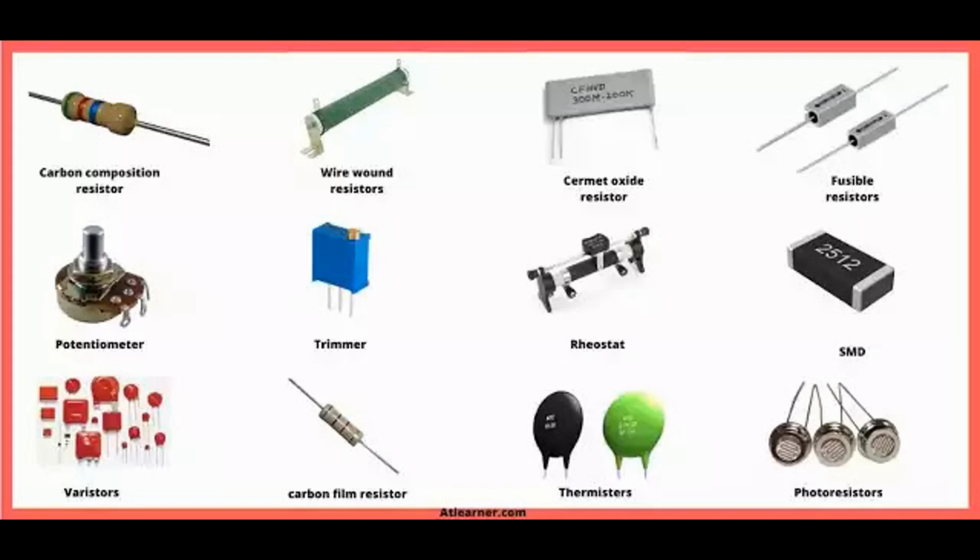Thermal management techniques. Heat sinks: metal components attached to heat-generating devices to increase surface area for heat dissipation. Used in power transistors, CPUs, and power supplies. Fans and forced air cooling. Fans are used to move air over components, enhancing convective heat transfer. Thermal interface materials, TIMs. Materials like thermal grease or pads are used to improve thermal conductivity between components and heat sinks. Circuit design considerations. Component selection.